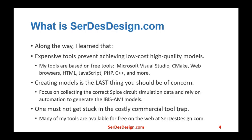Along the way, I learned that expensive tools kill all chances you have of achieving low-cost, high-quality IBIS-AMI models. My tools are based on free tools: Microsoft Visual Studio, CMake, web browsers, HTML, JavaScript, and more. I learned that creating IBIS-AMI models should be the last thing you concern yourself with when it comes to creating IBIS-AMI models. Focus on collecting the correct SPICE circuit simulation data and use automation.